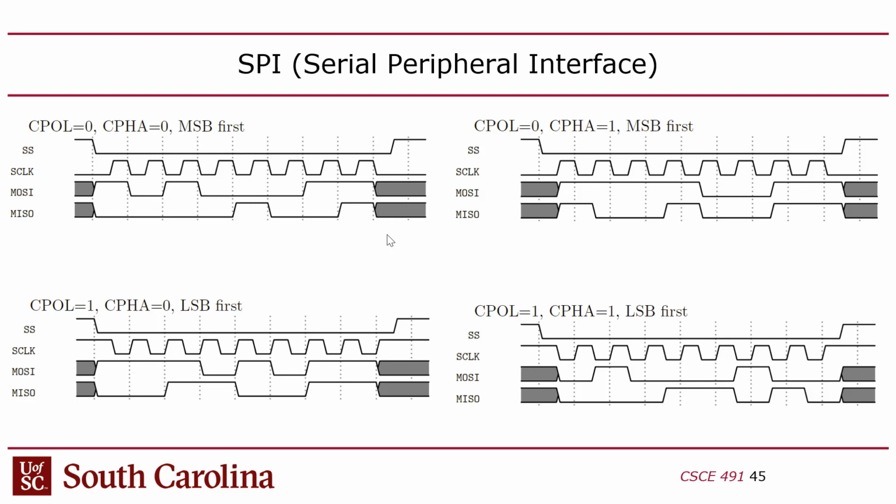It's just, usually it's not done because it would take the CPU's entire attention to see those transactions through, at least a low speed CPU, right? So that's why they use circuits to do that. Of course, you're limited in the number of circuits you have too, though. Like on an Atmel 328, there's only 1 SPI channel. If you need more than that, then you're going to have to bit bang the additional channels. You just don't have enough I/O on that chip, right?